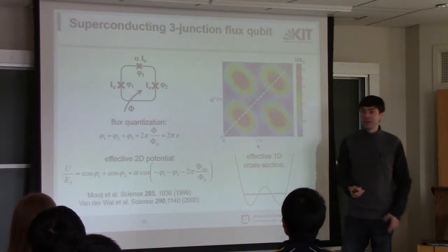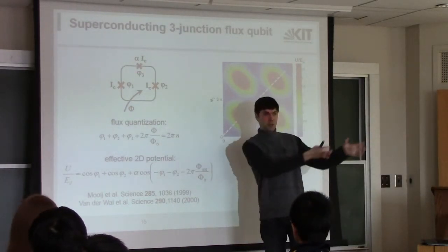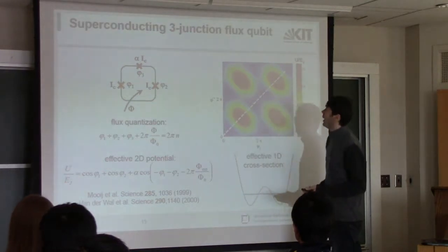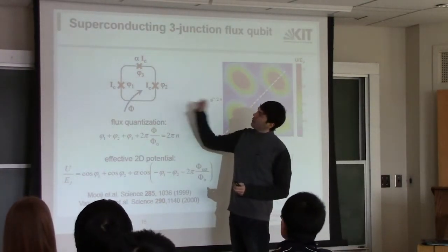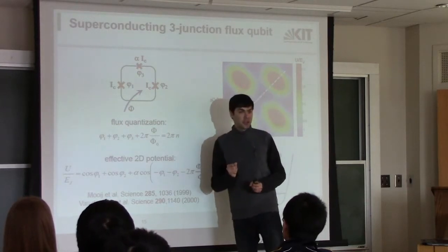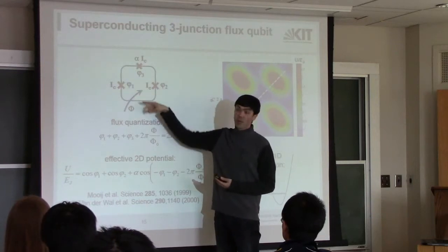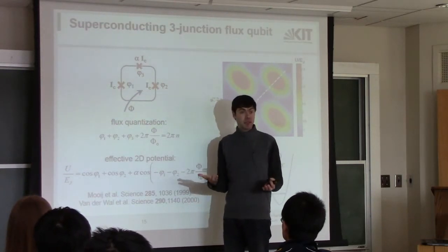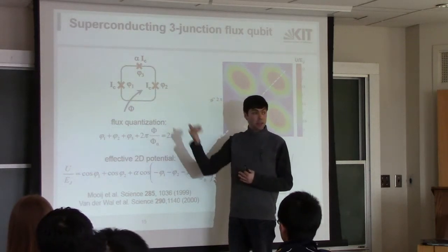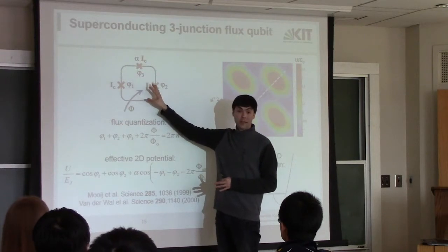Okay, so this was my introduction, and now we are going to talk about flux qubits, charge qubits, phase qubits. Flux qubit: it's a loop with 3 Josephson junctions. Conceptually, you would think you only need 1. A loop gives you an LC circuit, and you add 1 junction to create the anharmonicity, the nonlinearity that you need. Turns out, for practical reasons, it works better with 3.